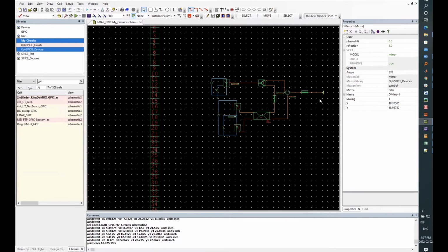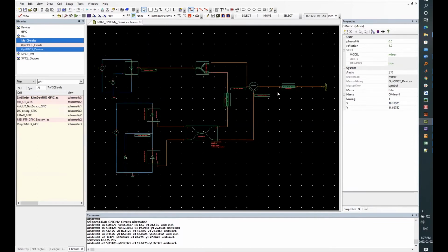The signal hits the target, comes back, and then at the bottom, we use the photodiodes and the directional couplers to interfere the signal that just came back into the chip with the signal that was traveling outside. So both of the signals are chirped, but one of them is delayed. The signal reflected back from the object has a time delay on it. So when you interfere the two, what you end up with is a beat signal, because there is a linear increase in frequency for both.